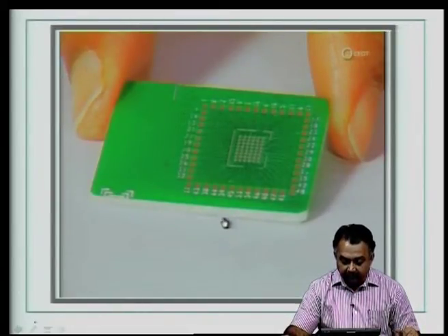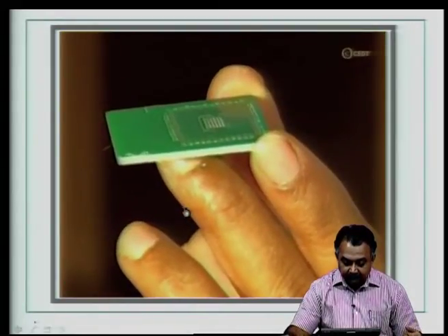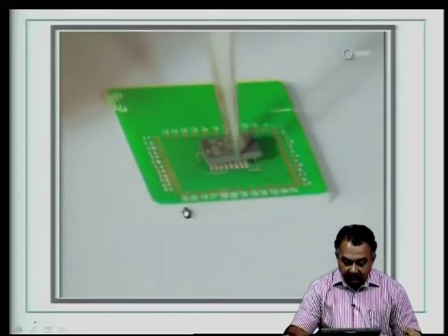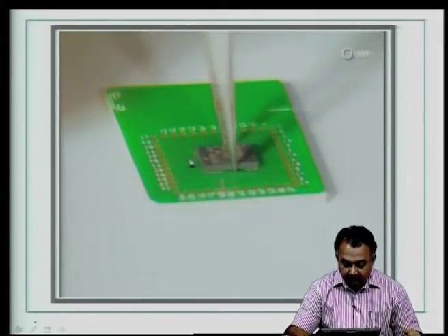Now, you can mount your BGA here and do a reflow process. So, you can see here this is the component that is placed, because here we do not have an equipment typically to place this, but you can see there is a package outline that has been generated. So, we will use this as an estimate for placing the package manually.